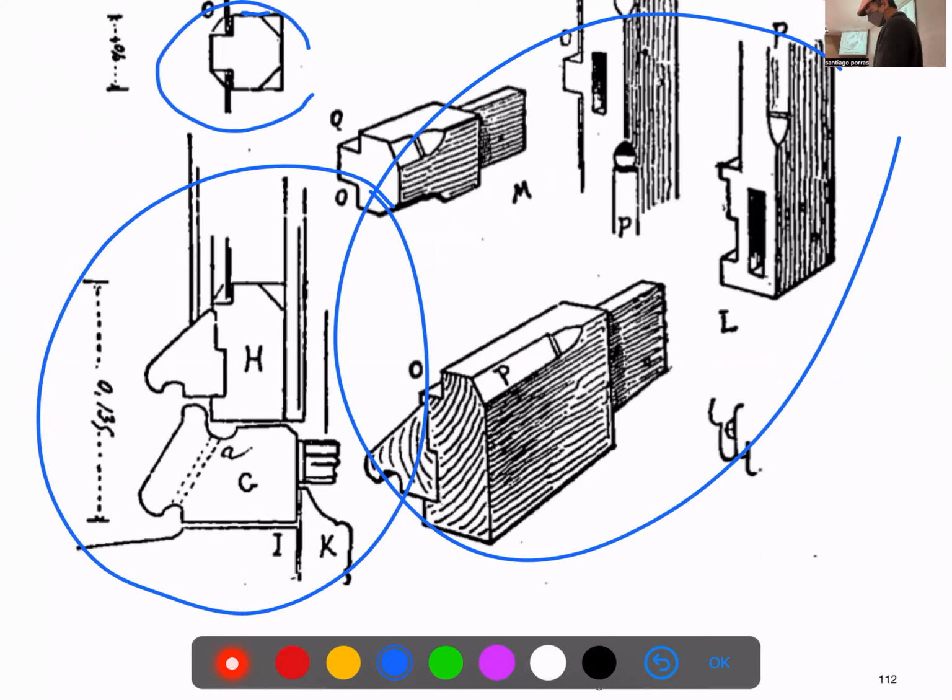Again, the wood is cut in those borders. Why did they do that? It's not only for decoration. It is because those borders usually suffer, have marks, they break. So if you have a small cut, it will be much easier to maintain, not only for being visually pleasant, right? Sharp edges always suffer, always have, how do you say, marks and bumps and so on.